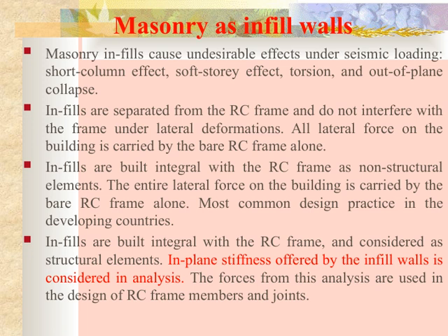Now, in many cases, these infill walls are separated from the reinforced concrete frame. This separation means they don't interfere with the frame during lateral deformations, so all the lateral forces are carried solely by the bare RC frame.